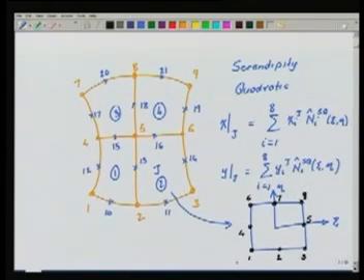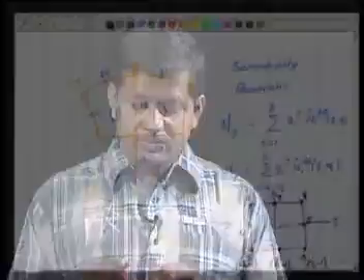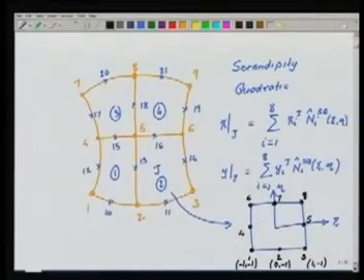This has coordinates -1, -1. This will have coordinate 0, -1. This will have coordinate 1, -1. So you see that this mapping takes us back to the same master square that we had earlier for the linear or bilinear map. Remember that we have this kind of a feature for the mapping. And so now, we'll say mid side.